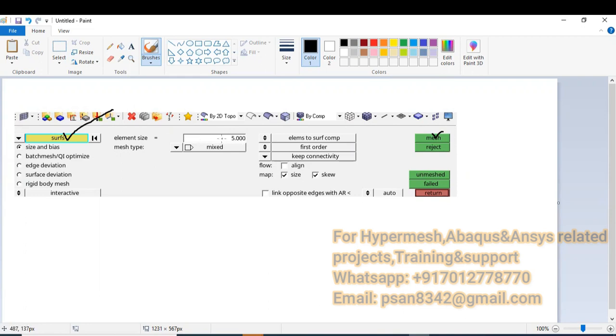This global size, minimum size, maximum size, element quality parameter, criteria, everything we'll discuss in detail. But as of now, just think some basic things you need to learn. This element size, whichever I have given here now, is 5 mm. So the software will try to give a mesh sized 5 mm. It will vary as per the geometry complexity.